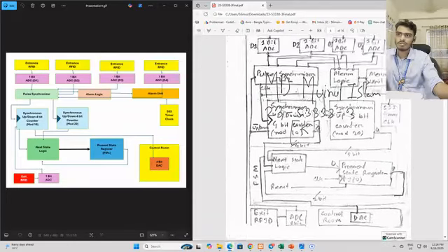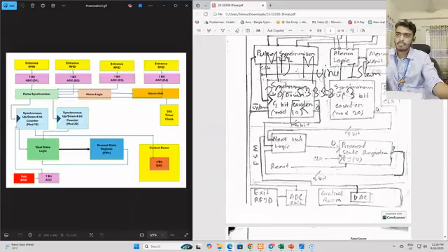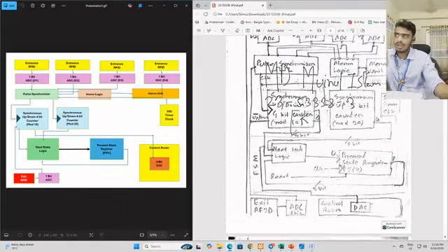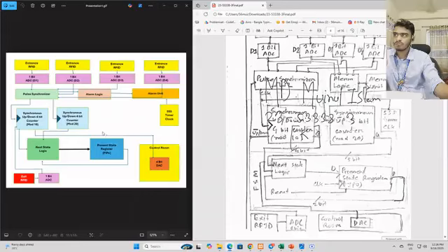I have given the block diagram fully here. I did not add the bit numbers on those areas; I have added them here. This is a 5-bit counter, so it returns a 5-bit output, and this is a 4-bit counter, so it returns a 4-bit output. And our state management is 3-bit. There is a typo here again; that should be 3-bit. Our state management system is a 3-bit register, so it returns a 3-bit output. So that should be 3. This is a typo. I'm sorry again for the typing mistake.